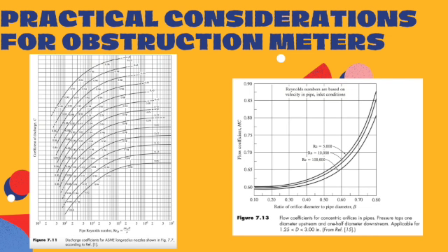As you can see, the separations of each line. The inlet pressure tap is located at 1 pipe diameter upstream, and the outlet pressure tap is located at the vena contracta of the orifice.